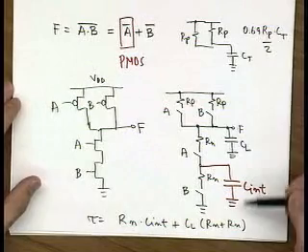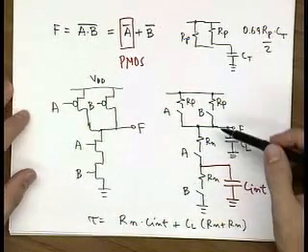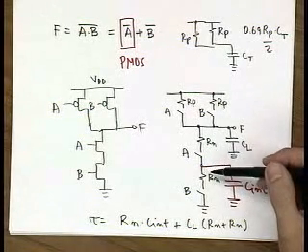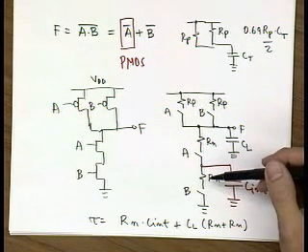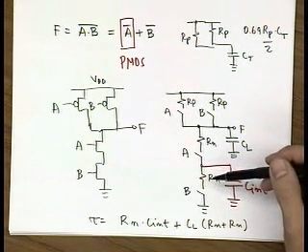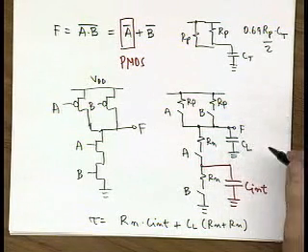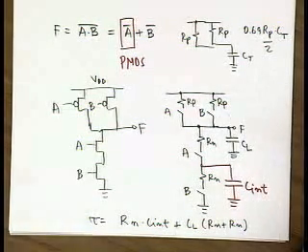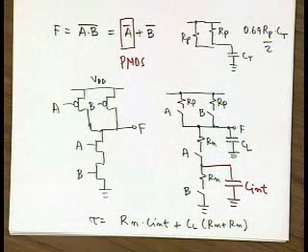So you see you have not only different delays, but also a huge delay mismatch because of the stack of NMOS transistors. When you have two transistors in series, you have two effects. You accumulate more capacitance due to this intrinsic capacitance, and your resistance also goes up. As a result, you will have a quadratic increase in your delay. That's really bad. For the pull-up, when you have parallel devices, they work together with each other. By adding more devices in parallel, you will have only a linear increase in delay, because you're only adding to the node capacitance. Your resistance still stays the same.